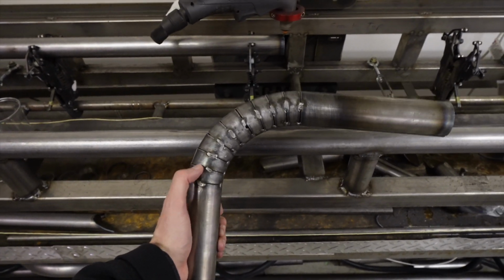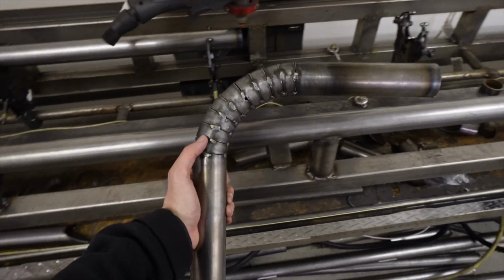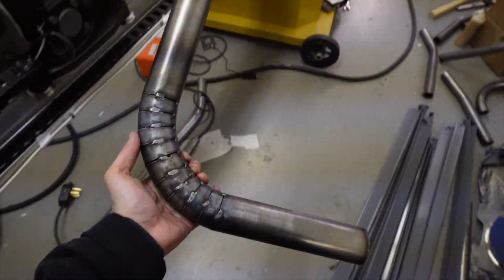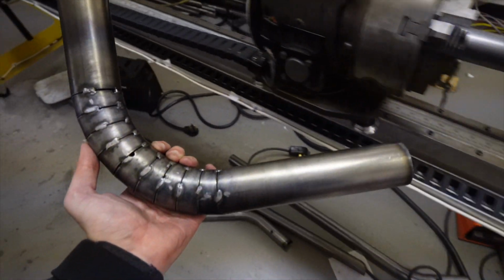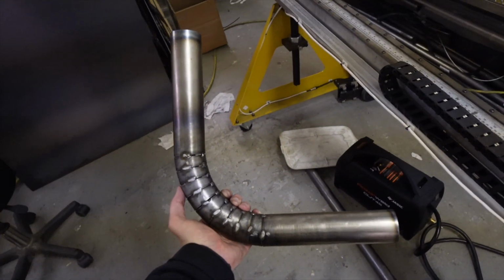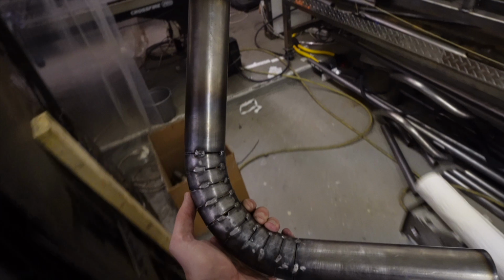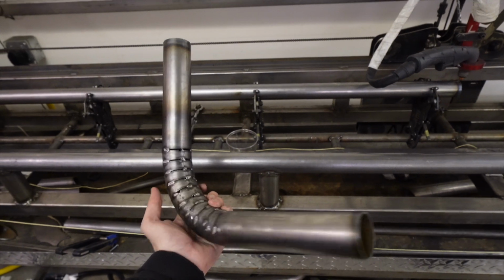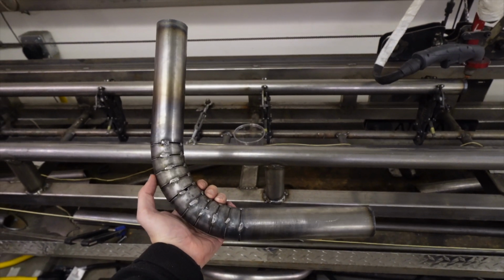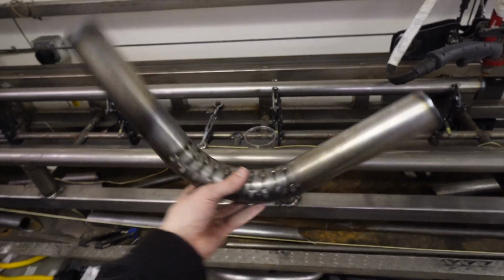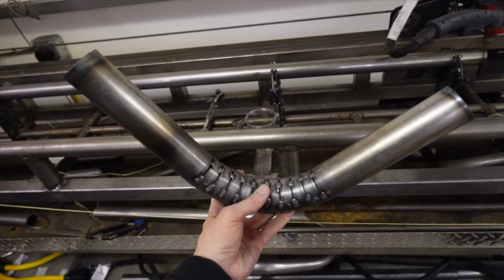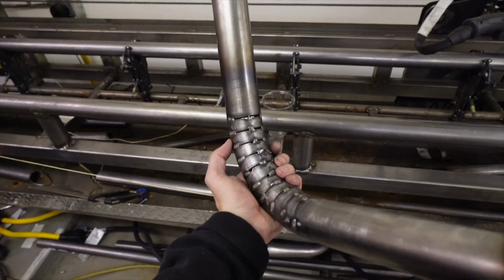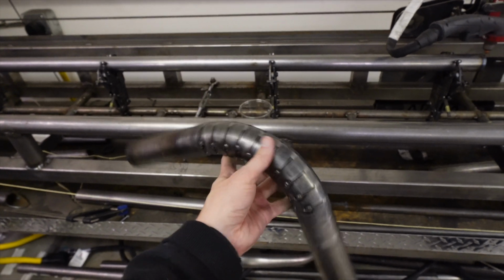But this bend radius can be anything that you want, and it will provide for routing of tubes, exhausts that the CNC tube bender can't do. The tube bender can only do certain bend radius. So this is a good first test. I'll take some measurements and just make sure that the calculations for generating the G-code to cut these parts are correct. Check with the welder just to see what they think about the gap, because that's not the greatest. That's a consequence of leaving the bridge that keeps them all connected.